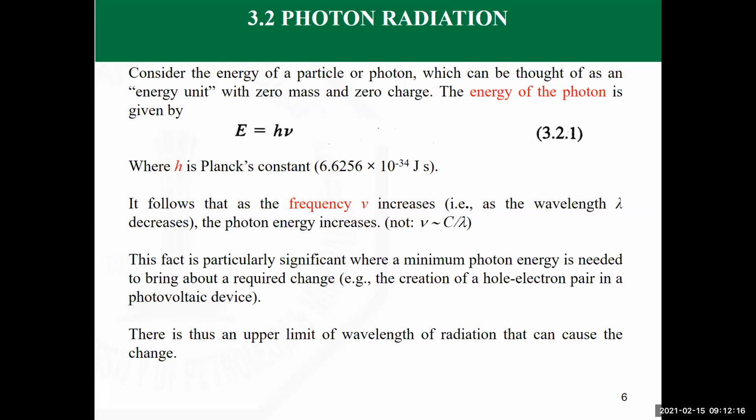Glass is transparent to short wavelength radiation, which means that the energy coming from a high temperature source like the sun can transmit through the glass. It gets into the inside of the car and increases the temperature of everything there. The emission of radiation from the car is from a lower temperature source, and this is what we call long wavelength radiation. Glass is opaque; it does not transmit long wave radiation out, which means that there is continuously energy in, but no energy out by radiation. And that's why it keeps on heating.